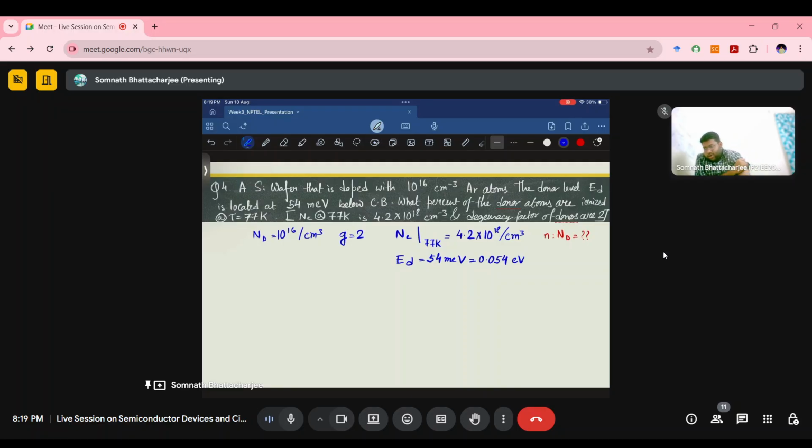The best option to start is towards this. To solve this, best is to get the value of the electron concentration first. So that is NC multiplied by e to the power of minus (EC minus EF) divided by KT. From this, you have to calculate the values.